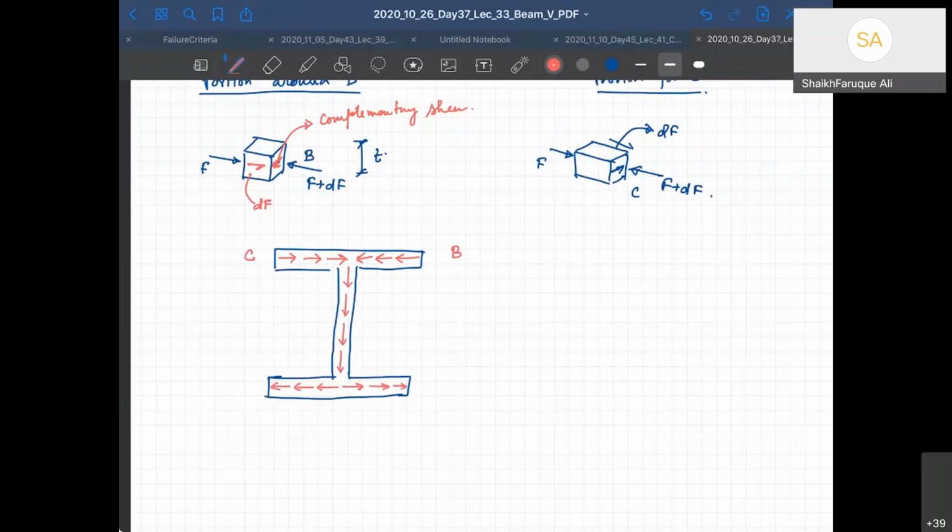So if you see this properly, it's like water flowing, right? It's like water coming from this end and also from this inlet. Both the inlet water comes and they join somewhere here and then they flow down and then again they separate at this point, one goes to this outlet, the other goes to that outlet. Okay, this flow of shear is called shear flow,